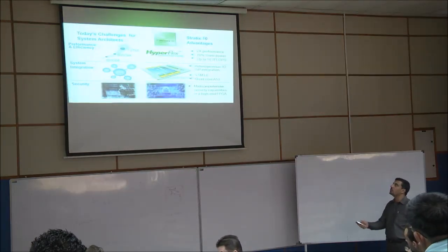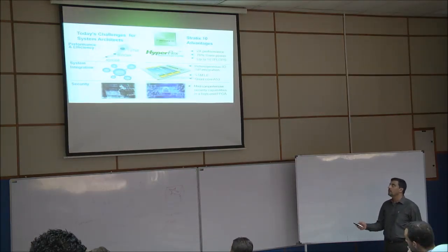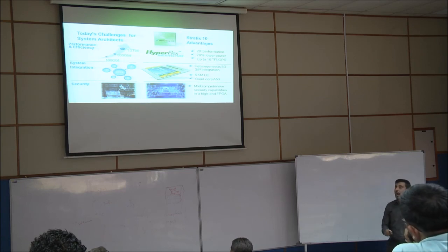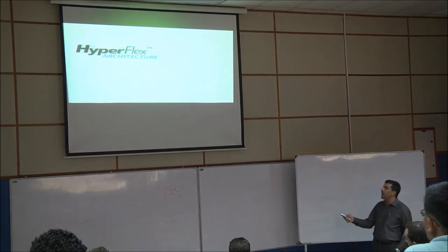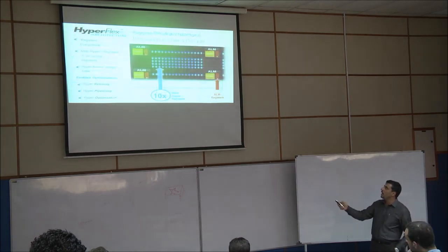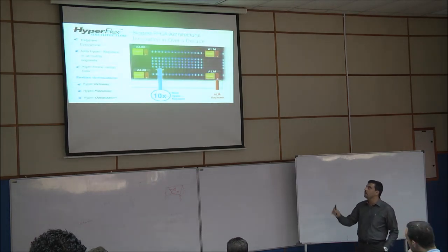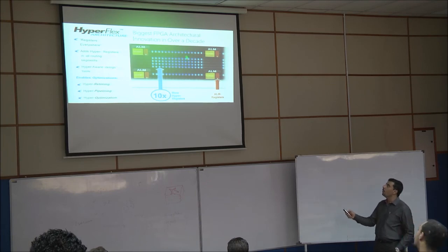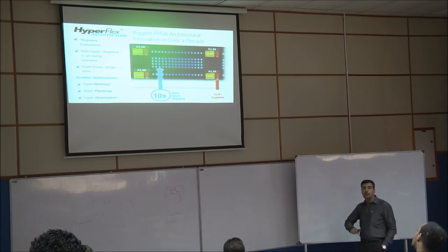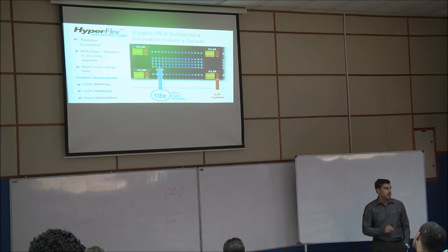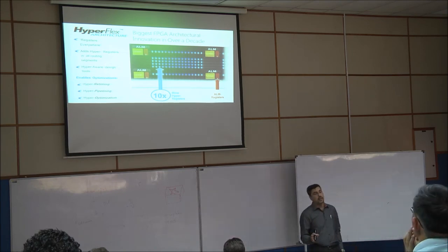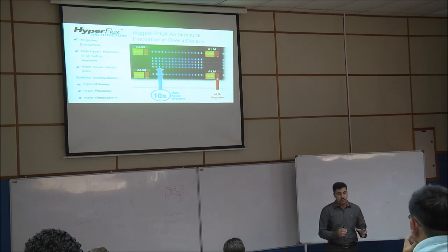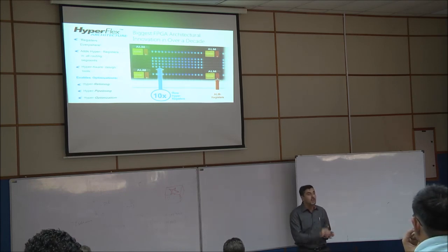So these are all the features of Lattice 10. The most important one I want to highlight is the HyperFlex register architecture. The meaning of HyperFlex architecture, I'll go directly to the point. You see this blue dot? Actually, we call these registers. After a few years of fabrication for FPGA, they realized the routing delay is more than the register delay itself.